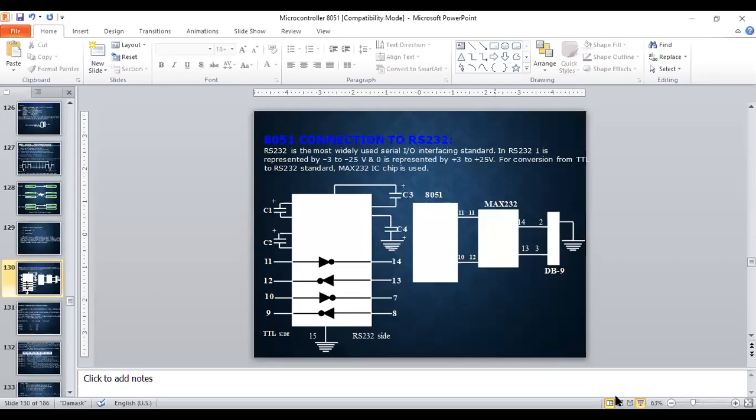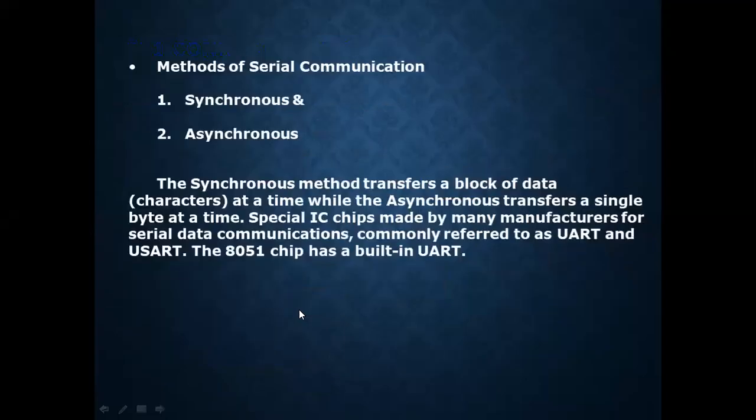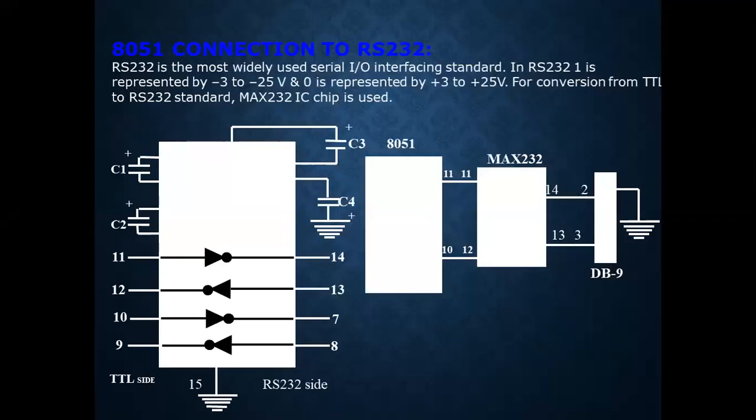Now we will see that this 8051 chip has a built-in UART. So by default, this 8051 microcontroller participates in universal asynchronous receiving and transmitting. So here in 8051, to communicate with serial communication, we need this MAX 232 chip.